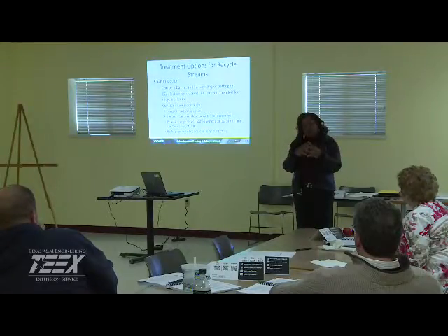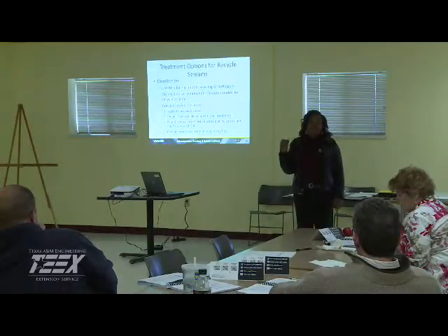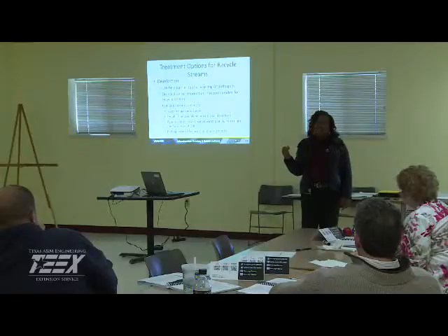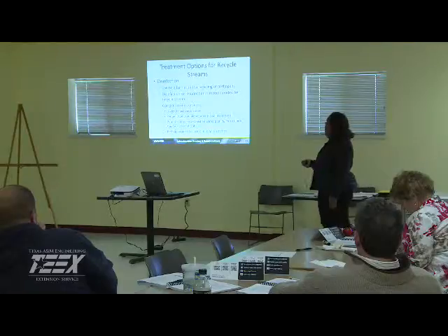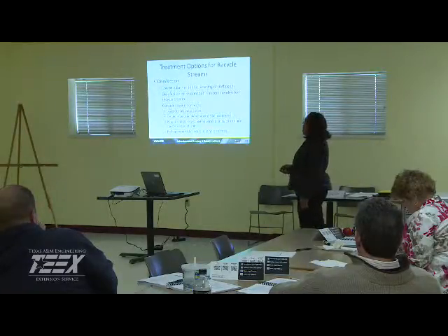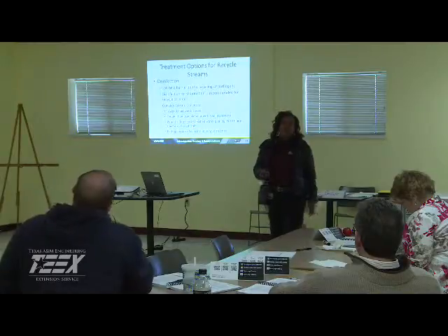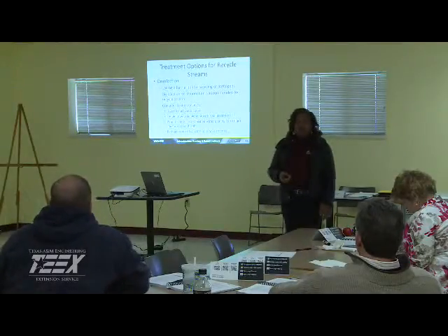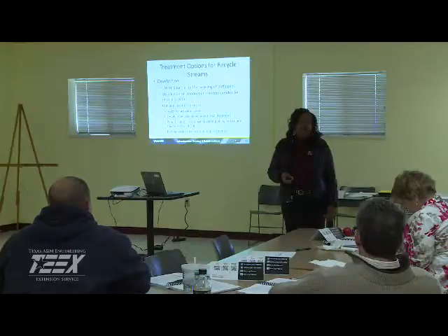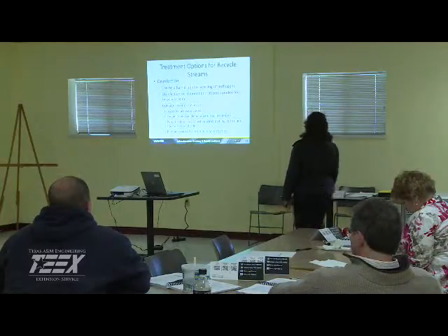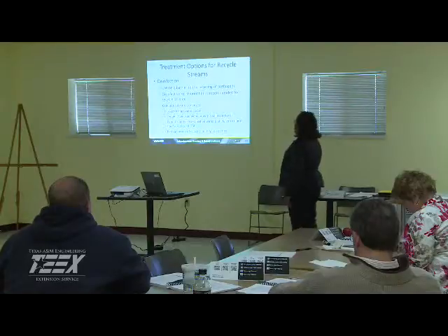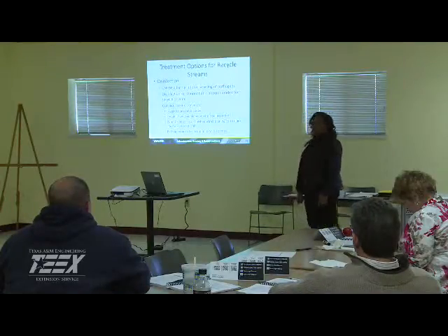Now I have the formation of, yes, those trihalomethanes and haloacetic acids. What impact is that going to have? And you want to look at the pathogens of concern in the recycled streams. Is it just Giardia and Cryptosporidium, or are we looking for other things such as E. coli? So, lots of things to think about when you're looking at the treatment options for the recycled streams.